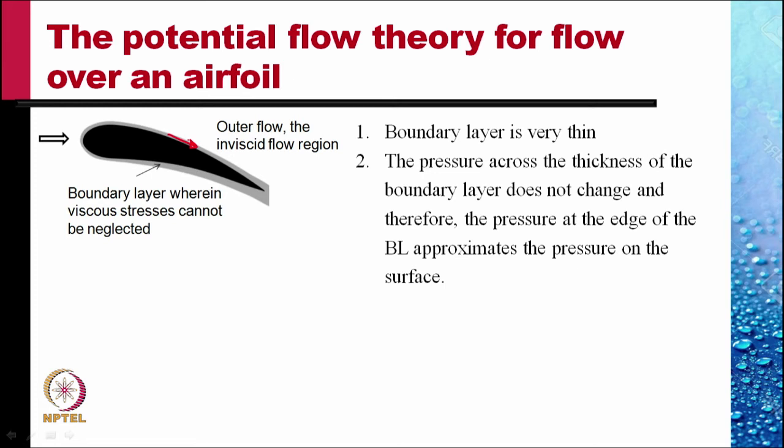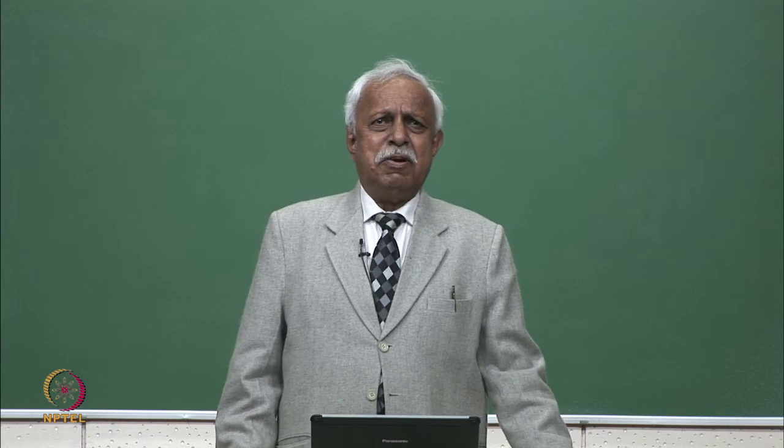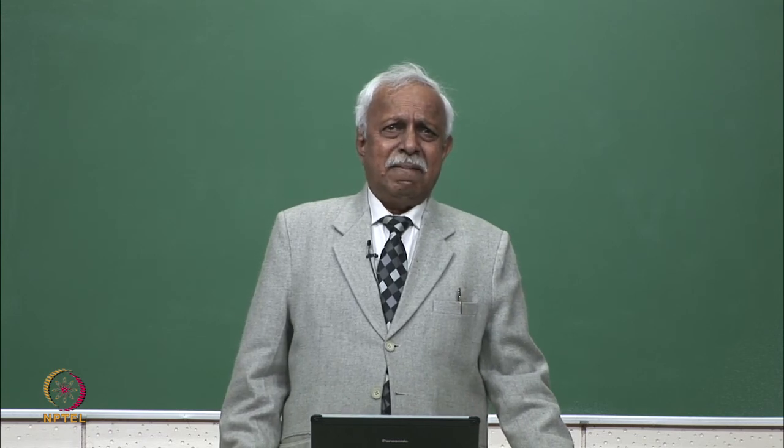And that is what makes the potential flow theory so powerful in aerodynamics. We can use completely aerodynamic solutions, forget about the no slip condition at the surface of the aerofoil, treat the surface of the aerofoil simply as an impervious body, and calculate the pressures there.